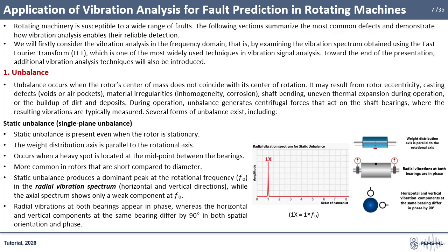Rotating machinery is prone to various faults. In the following slides, we review the most common defects and show how vibration analysis can be used to detect them reliably. The analysis is mainly performed in the frequency domain using vibration spectra obtained by the fast Fourier transform.